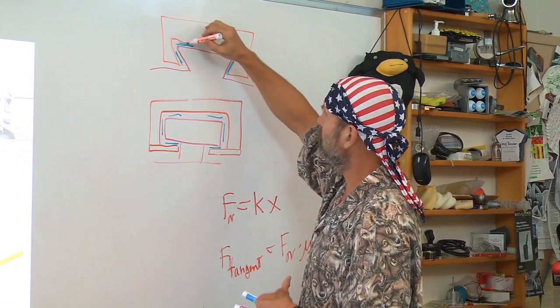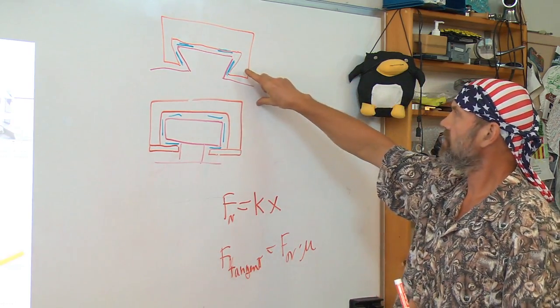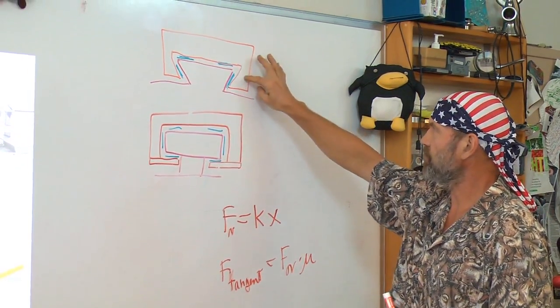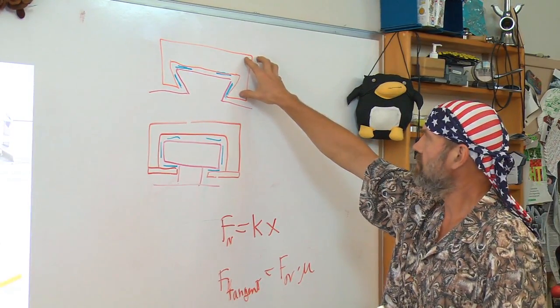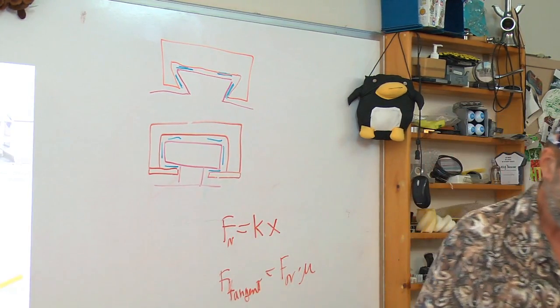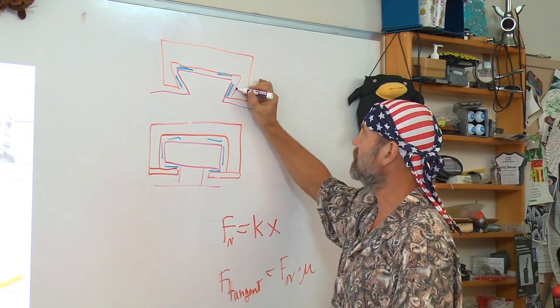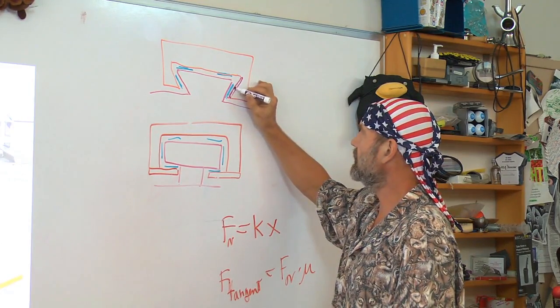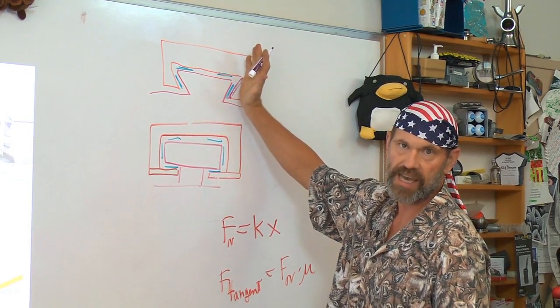Now, when we come into preload, again, you'll see that here there's no way to really preload this arm well without the whole structure being a little too soft. And then what will be introduced is what's called a gib, or a tapered element. As the taper moves in and out, it closes and changes the gap.